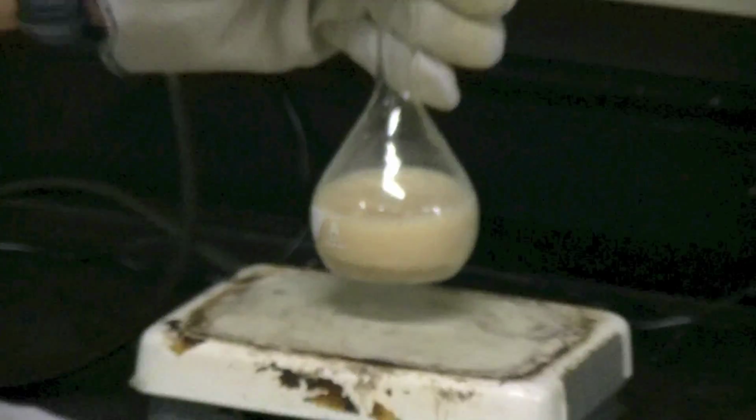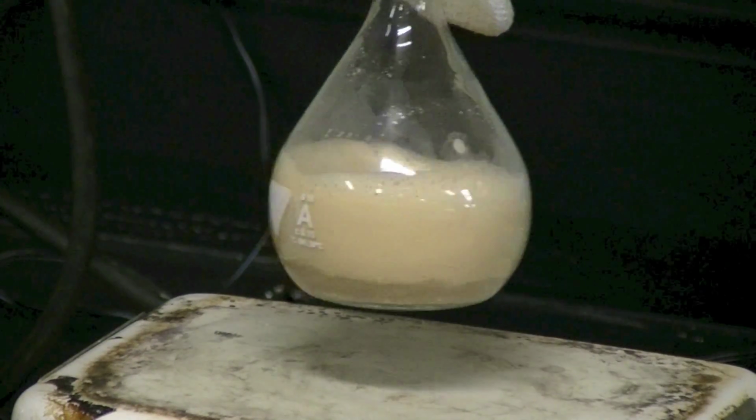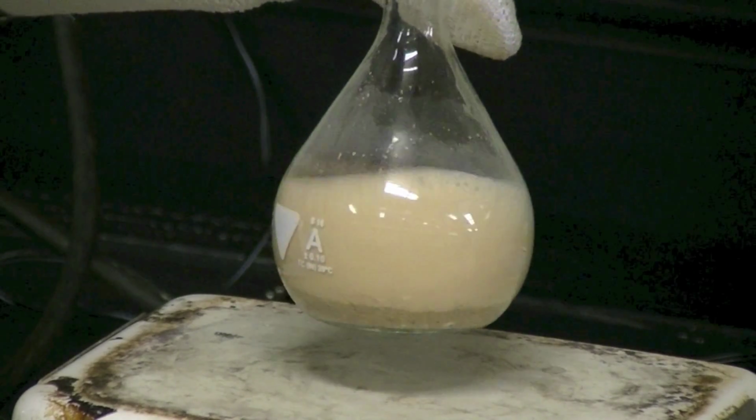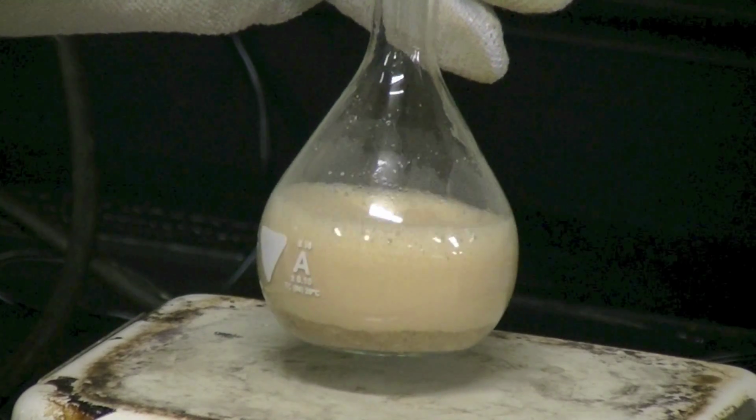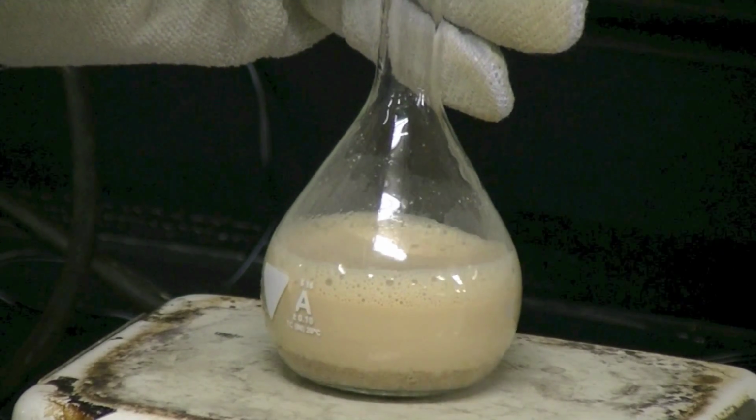The most common deairing method is boiling. Other methods include vacuums. When using the boiling method, use a hot plate or a Bunsen burner to apply indirect heat. Heat the slurry until it comes to a full boil.